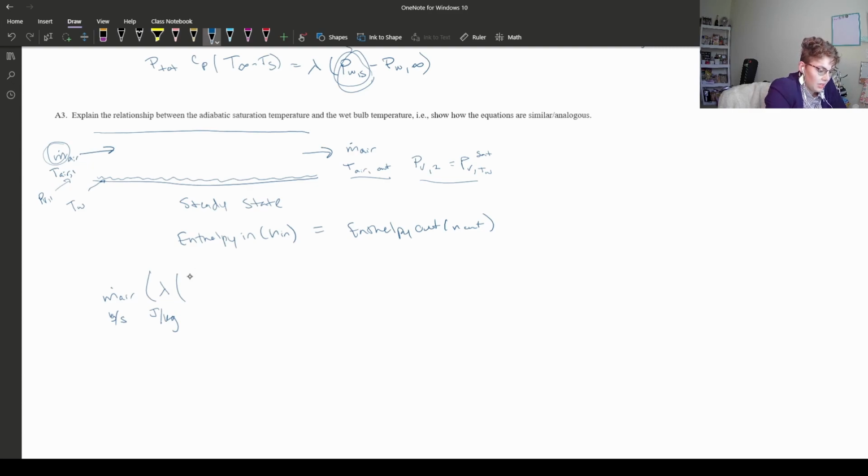For our initial concentration going in, we have the partial pressure of the water going in over the gas constant times the temperature. But since we are using the mass of air here and the partial pressure of the water vapor here, we also need to include the specific volume of the water vapor in the air, and that we can do by using the total pressure over RT.